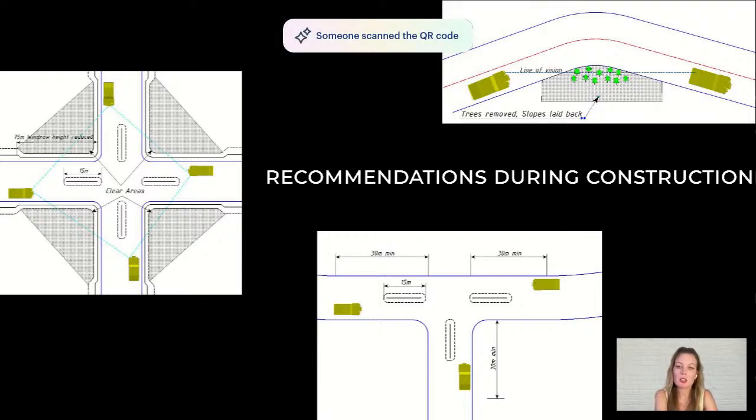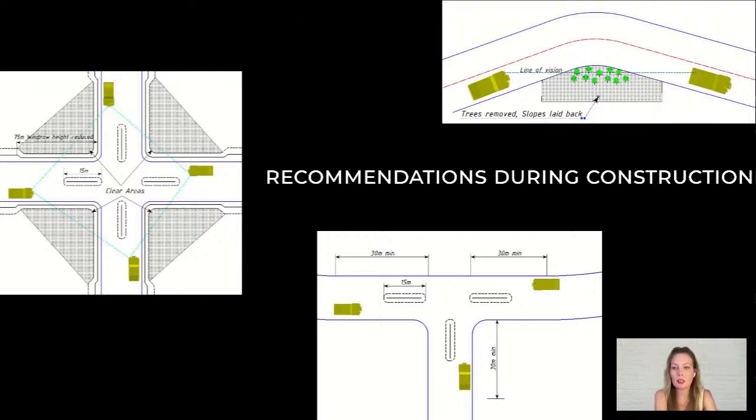For intersections, it's best to avoid crossing more than two roads at a single point and to steer clear of Y-shaped intersections which do not meet at right angles. Ideally, the straight section of the road should be at least 30 meters on both sides of the intersection. To enhance safety, you can use a small windrow at the intersections, and it will serve as a visual guide for drivers.